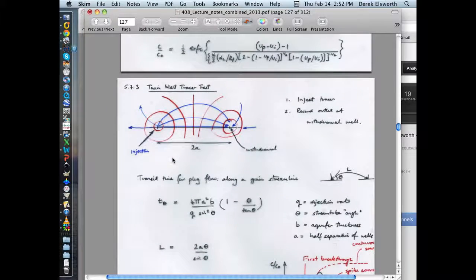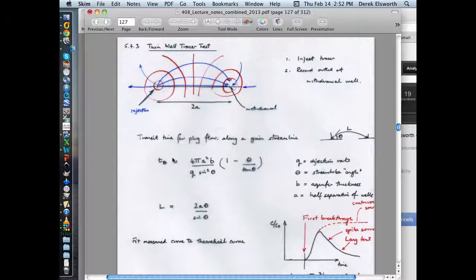So you could do a more sophisticated test that now, you probably know from, if you remember from talking about your 452 class, if you ever talked about doing well tests in that, there are a variety of different well tests you can do. So you can do a slug test. You take a single borehole, just like this past one. You push fluid into the well. You measure the rate at which it goes into the well, and you use that to calculate what the permeability is.